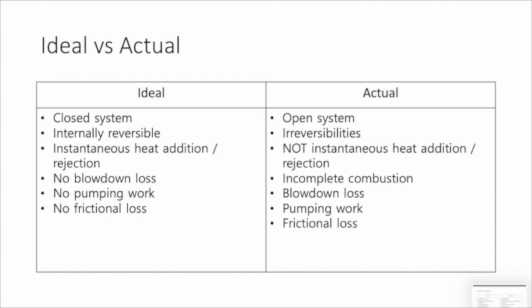Let's go back to the air standard assumptions. Combustion is replaced with a heat addition process, but combustion is conducted in the real world. This contributes to taking time to combust the air-fuel mixture, which means not instantaneous heat addition, and incomplete combustion due to the possibility of lack of oxygen in the cylinders. The rest of these three losses, blowdown loss, pumping work, and frictional loss, are going to be explained on the later slides.